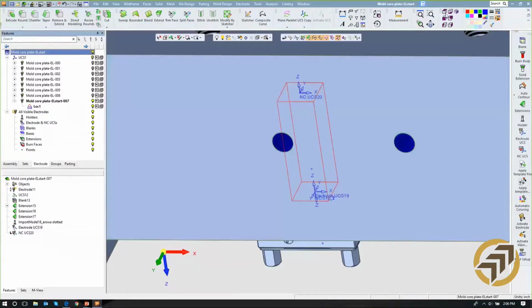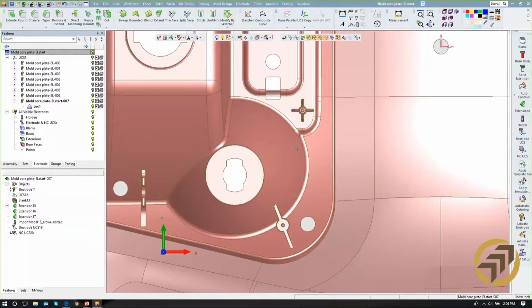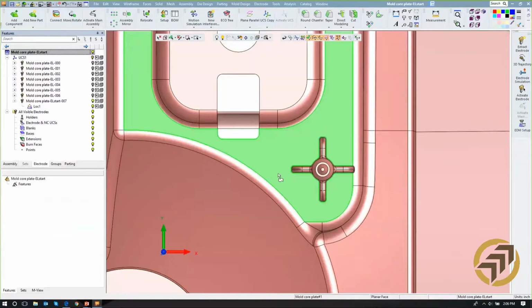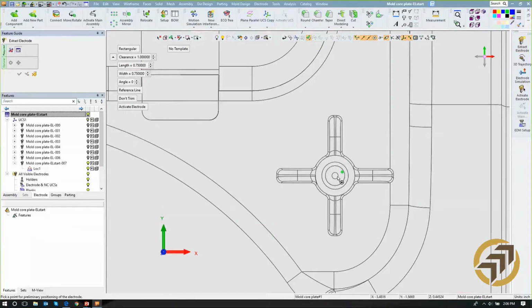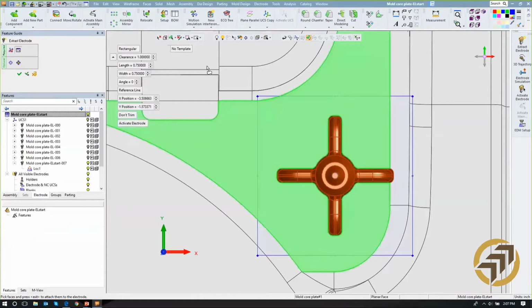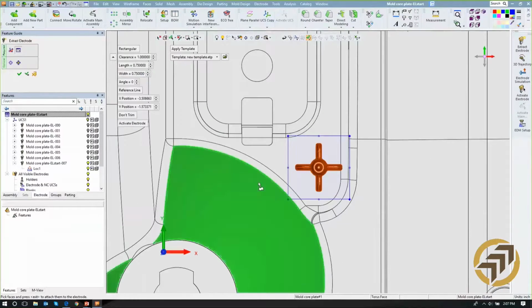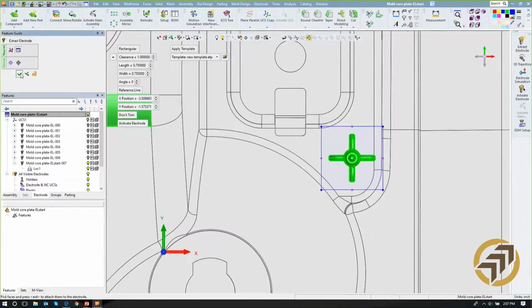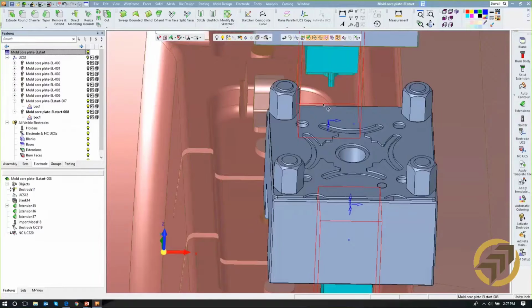Go back to our plate that we're working with. The thing about the use of the template, it doesn't necessarily have to be working with similar geometries. It's the method that you've used that's the most important. So perhaps we'll zoom into this area down here, strike a position that we want, and from the template, let's say what we want. Well, new template, there it is. We'll go ahead and use those faces and create the electrode. So it remembers the sequence of events that we went through, all those steps, and then reproduces them on the next electrode.